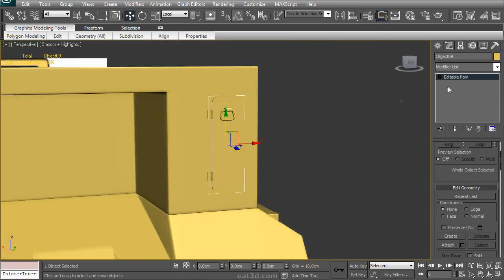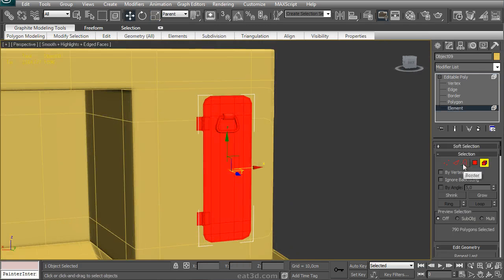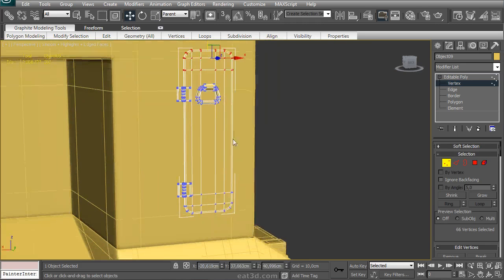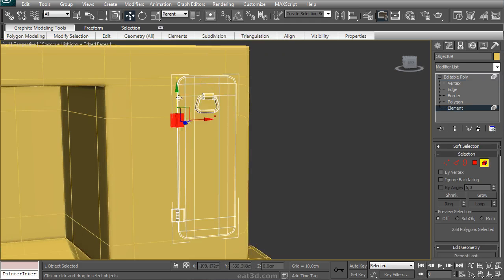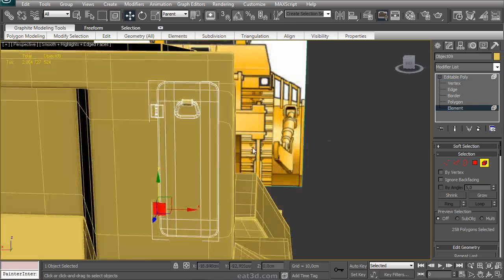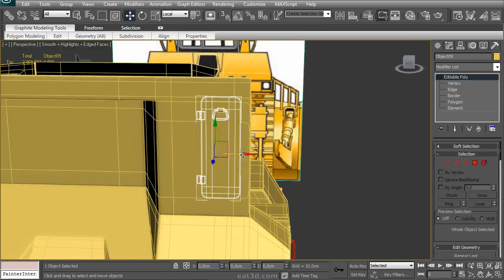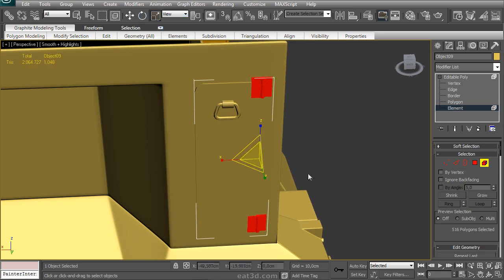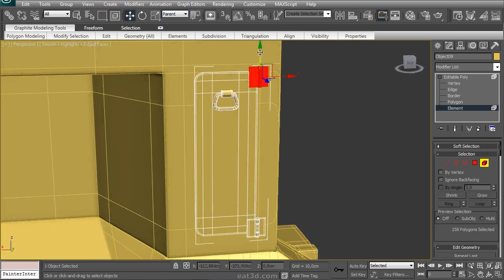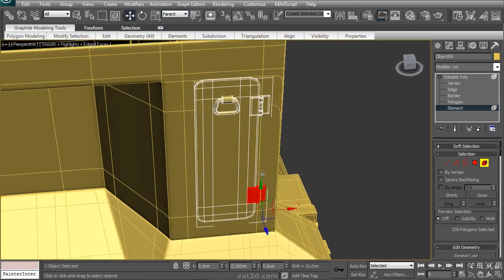Same trick with the hatch on the other side. You've seen me do it before. It's just the same exercise. Move it over. Then do a few selections to change the global shape. This one's just slightly bigger, slightly higher. Not that much change. And the hinges are actually on the other side, so I'm just moving them around, rotating them, and repositioning them. They're also a bit larger, so I upscale them and then move them back into position.